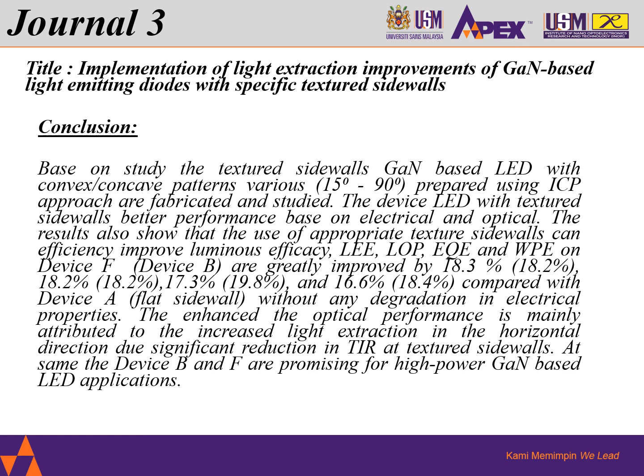The textured sidewall with the concave pattern was able to be prepared using ICP dry etching during the fabrication. The LED with the structured sidewall has better performance in terms of both electrical and optical.